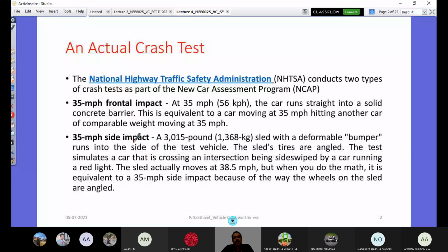Why these specific speeds? 35 miles per hour is an average vehicle speed that is accounted for. With these speeds, the crashworthiness would be realized in reality, and the safety system can be supporting. Of course, at high speeds, in real frontal accident scenarios, it may not be possible, but restraint systems still work at that speed, because the deployment of passive restraint systems is quick enough within these speeds.